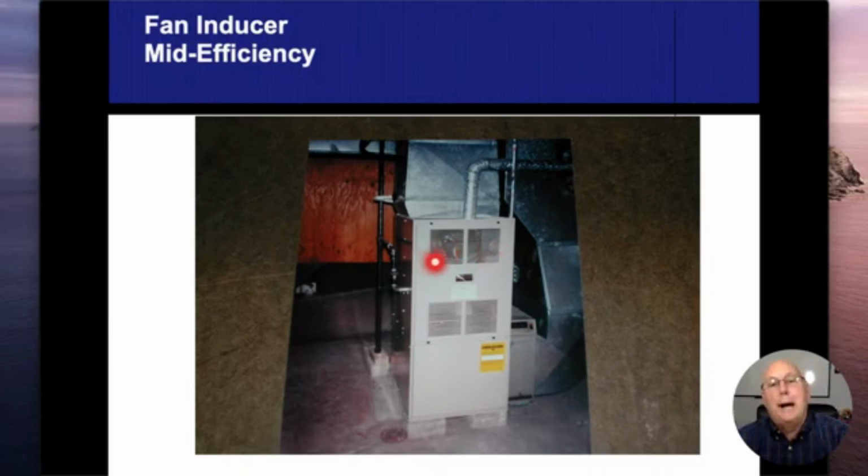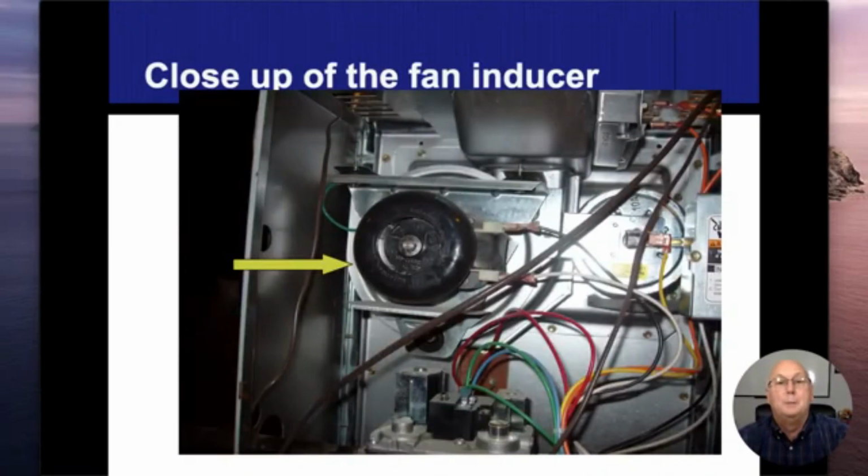And everything goes to the housing, and I'll show you a closer up picture of it in a little bit. But everything goes to the housing of the inducer fan. If the housing of the fan is plastic, then my vent and vent connector need to be plastic. If the housing of my inducer fan is metal, then my vent connector and my vent need to be metal. Plain and simple. All right. And I'll open that up and see.